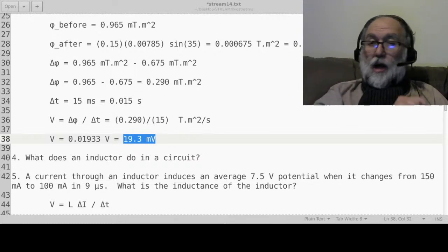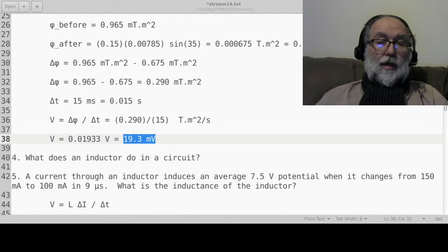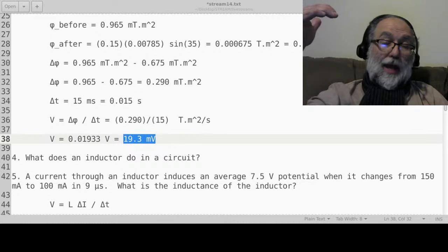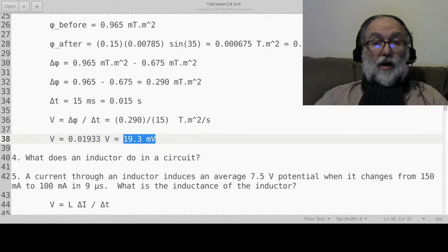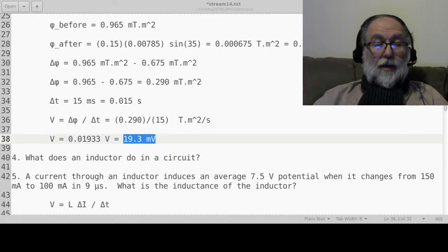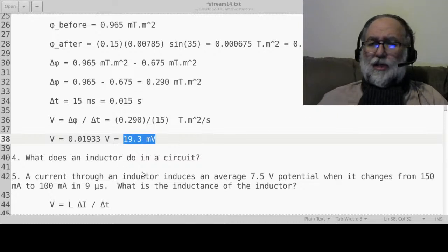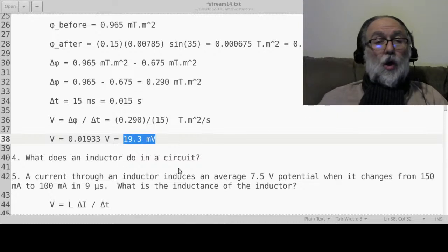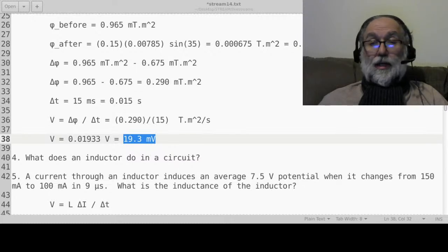Okay, so as long as it's that 1 amp current going through, the inductor is happy. But as soon as you try to increase it to say 1.1 amps, or decrease it to 0.9 amps, then there's some energy involved with that, because the inductor is resisting the change. Okay, so a little bit more subtle, but that's it. So that's why I asked this question. I wanted to make sure that people understand intuitively what an inductor does in a circuit. And again, it resists changes in current.